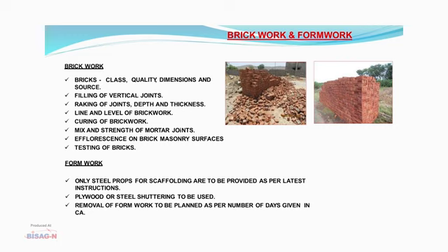Mix and strength of the mortar joints has to be ensured time and again at various stages of construction. Efflorescence is to be avoided on the brick masonry surfaces. Also, random testing of the bricks has to be carried out at regular intervals.